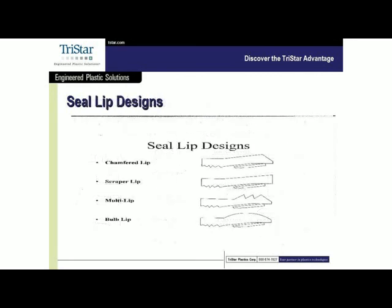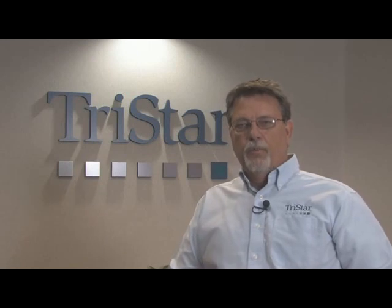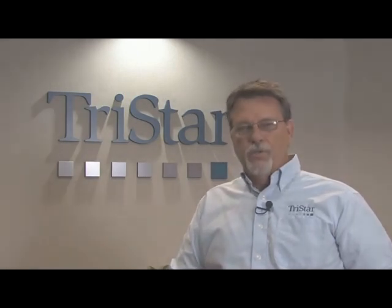So the four primary lip seal designs, and there's variations on these themes, but chamfered lips, which we'd be using primarily in reciprocating bidirectional sealing. If you've got an application where you want to utilize a spring energized PTFE as a scraper, we can also design a high point scraper seal. Multi-lip seals, where we're in essence generating a labyrinth effect, and what really is key here is being sure that we generate the right amount of spring force on that very small footprint area. And then finally a bulb lip, which is kind of a universal design where we're using different types of helical springs and matching those helical springs up, and we can use cantilevered beam too, but matching those up to a much broader footprint area and spreading out the forces, if you will.